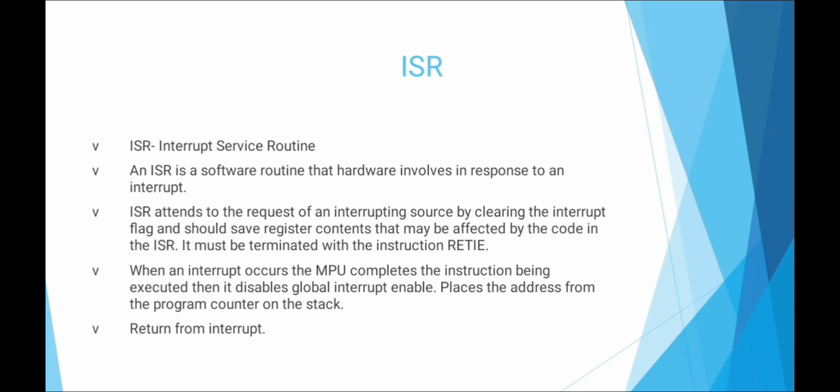It must be terminated with the instruction RETI. When an interrupt occurs, the MPU completes the instruction being executed, then it disables global interrupt enable, places the address from the program counter on the stack, then returns from the interrupt.